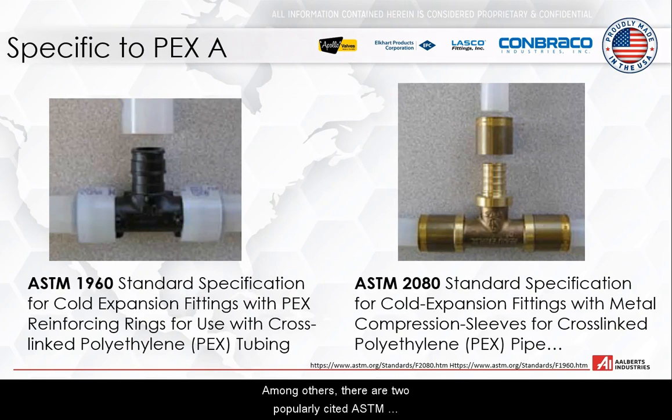Among others, there are 2 popularly cited ASTM standards that have to deal with PEX-A tubing. PEX-A is fastened by expanding the tubing, inserting the fitting, and allowing the tubing to close back over the fitting, known as cold expansion. The first standard, F1960, uses a plastic insert fitting with a PEX reinforcing ring. The second is F2080, which uses a brass fitting with a metal compression sleeve for cold expansion. Neither the reinforcing ring nor the metal sleeve receive a secondary crimp.